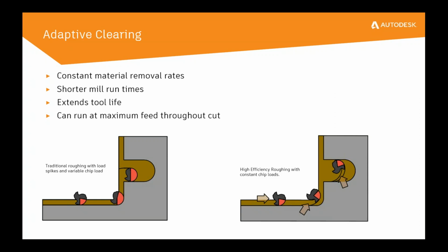So the advantage of that is, A, you never bury your cutter, which means 2 things. One, since you're not burying the cutter, you're not going to have to adjust your feeds and speeds to run slower. It maintains a constant chip load, so you can keep running at your high speed. Secondly, since you're maintaining that constant chip load, you're also improving your tool life. So your tools are going to last longer, your machine's going to be able to run at higher speeds, and you're maintaining a constant cut.